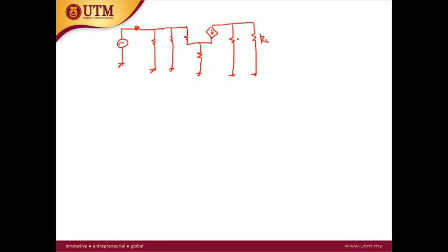Yeah, this is RL, this is RC, the current source is GMV pi, and this is RE, this is R pi, this is V pi, this is R2, R1, and then this is 600. So this is VS. Okay, let's calculate the AV. AV is defined by the voltage across the RL over the Vin. Vin is the input voltage. It's not Vs, so Vin.